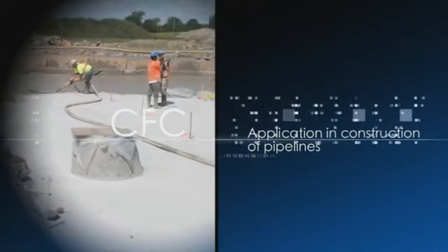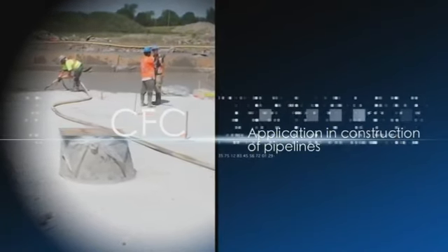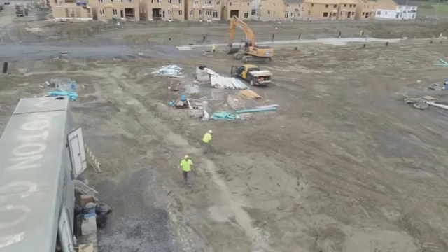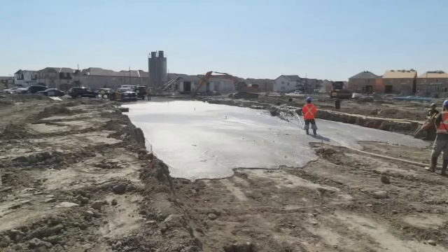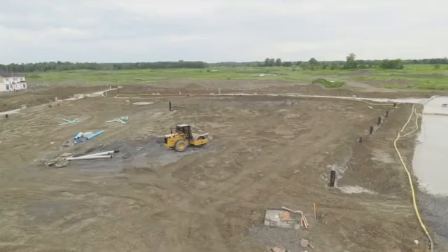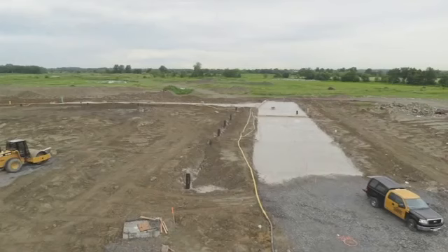Application in construction of pipelines. Cellular concrete protects pipelines very effectively from external forces, impacts, dynamic influence, and so on, while at the same time it is a perfect thermoinsulator, which allows reducing the excavation depth with an obvious economic benefit. CFC is also easy to cut with any type of tool, including a hacksaw, and to pour in the places of repair, forming a monolith.